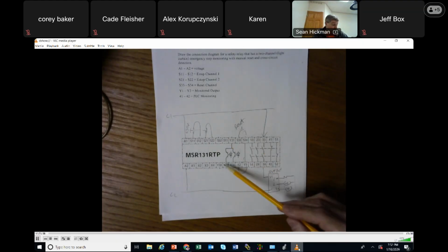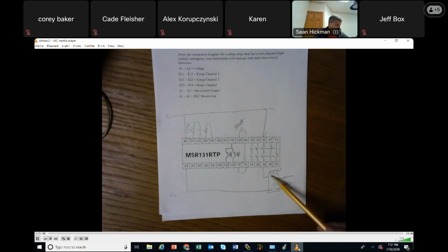If the safety relay brings down the voltage that feeds the card, I'm pretty sure that none of the devices that are wired into the card are going to work. You know what I mean? So that's another way to do it, is bring down the sourcing of your output module. Jeff, that was too fast. I couldn't see what it said. You might have to type that again or just copy and paste because I missed it.